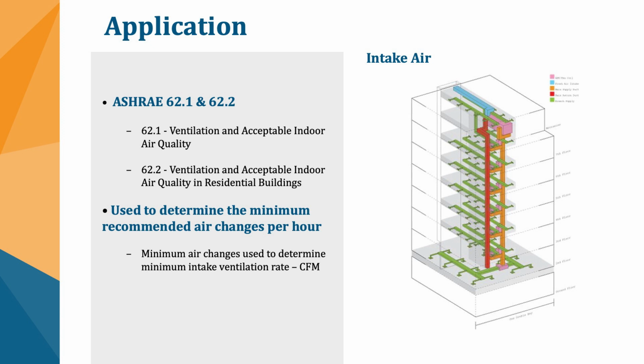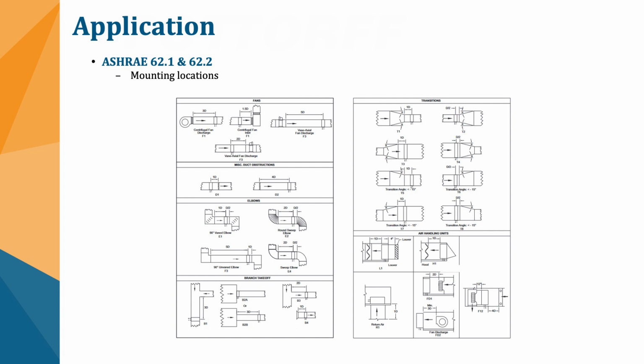Now you could do it a little more accurately by actually measuring the amount of airflow that you're getting through that ductwork. If you're actually measuring that airflow, you're going to be using some type of probe. It could be pressure differential, it could be thermal dispersion, but you want to have a pretty accurate airflow measurement for that.